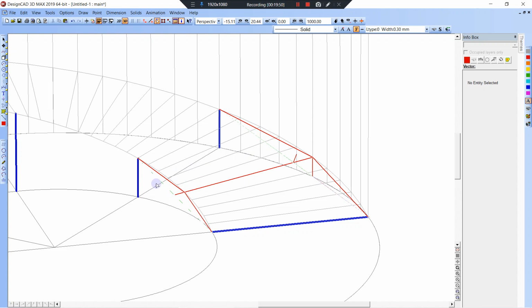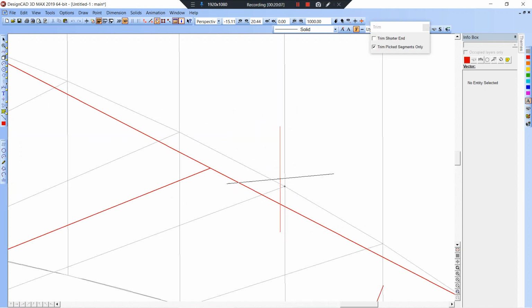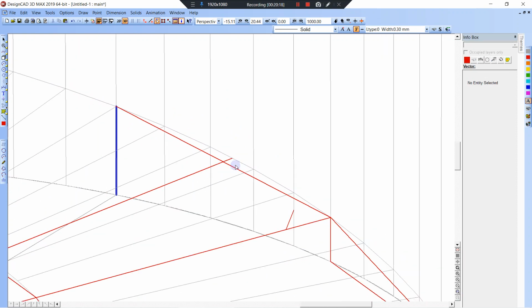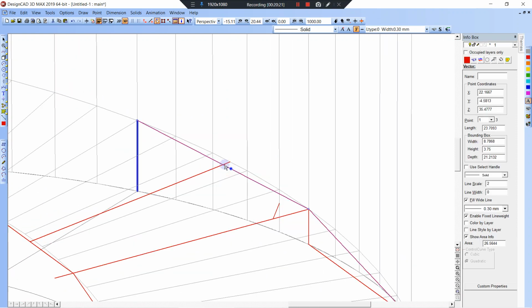And then we do the same thing, V, Control K, enter, and then you would do the same thing. You'd trim that out to the, you know what I can do is I can turn that into a line. V here, here, and then I can trim it out to that. All right. Delete.